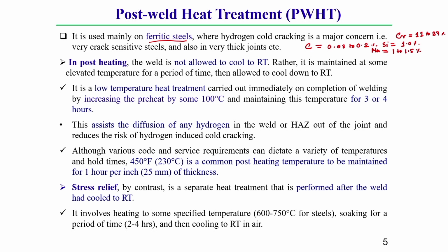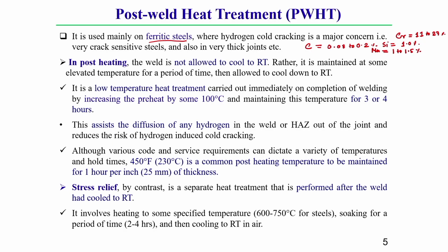It possesses a microstructure which is purely ferritic. It is also magnetic and has very good ductile properties, so it is a ductile type of steel. Keep in mind that in annealed condition it develops its maximum softness, ductility and corrosion resistance.